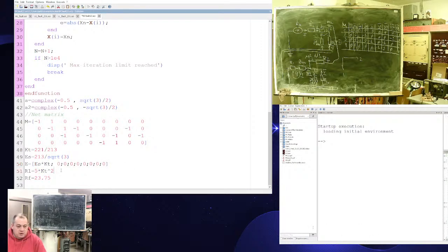Yeah, what about the resistor? This R1 is a mimic for the middle voltage cable network. I said 5 ohms just for being a round number. But if I'm reducing to the secondary voltage, I need to apply the reduction factor squared.